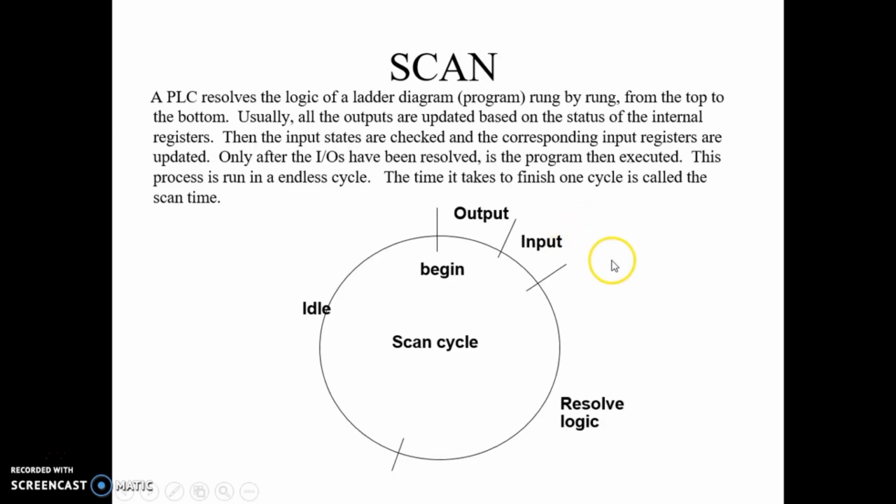Now how PLC works? PLC can scan output images as well as input images, and it also scans the program which is preloaded by the user as per their need. So at the beginning it delivers whatever output image is created by PLC as per previous status of the program.